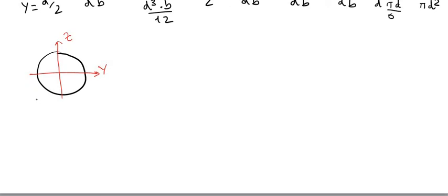If we represent here the normal stress, we have a maximum of compression here, that was equal to a certain value. We have a minimum tensile stress here that was lower, so what we expect is that the neutral axis cuts the cross section somewhere in the negative value of the y-axis. This was as we saw before.